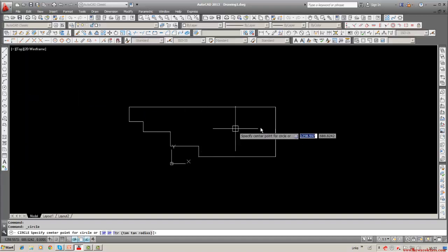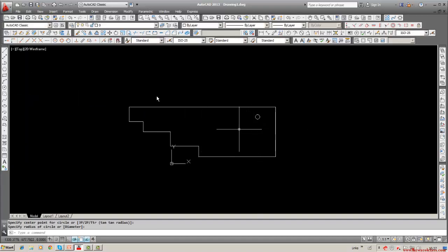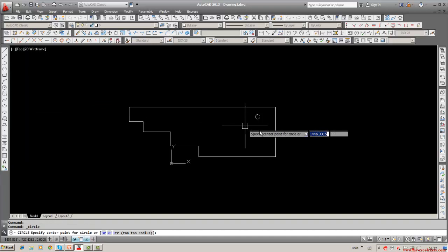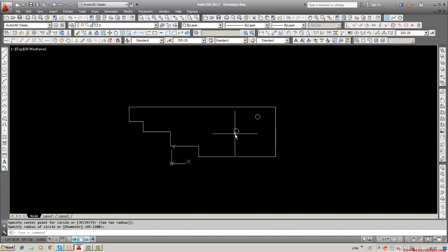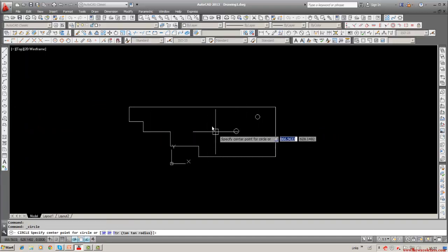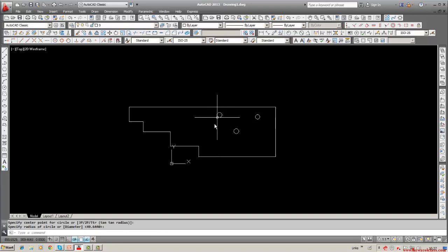Suppose this is a plate, and besides there are holes also inside, like this, 2, 3 holes here. And you need to know the distances from one reference datum. So for that, you dimension from that reference datum in x and y coordinates, and then it is easier to feed the coordinates on the machine, and you can machine the component.